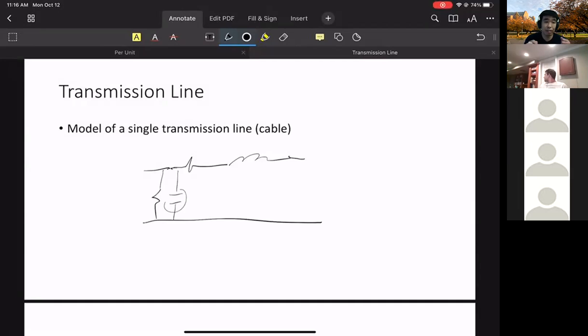So these two elements are more standard. Whenever you have a wire, you will have a resistor, and when you pass a sinusoidal current along the wire, it will look somewhat like an inductor. That's what always happens when you have a wire. But where does the capacitance come from? Why does the transmission line model have a capacitor inside of it? And when can we ignore the capacitor and when can we not? That requires some work to get to.